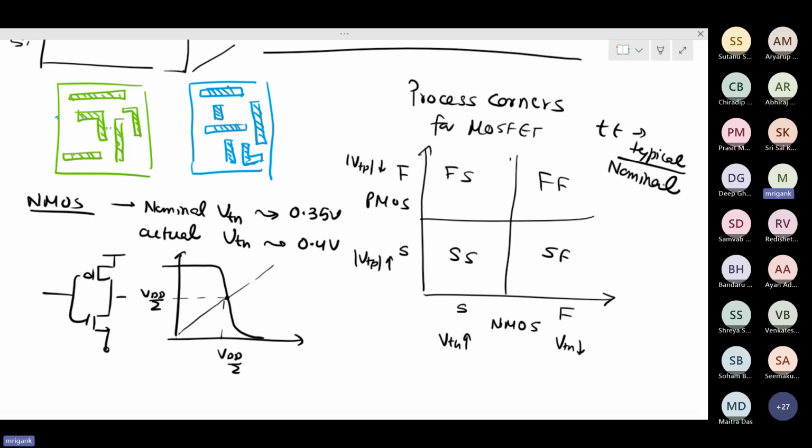In this LTspice, you may not get that kind of model. Right now in this model, you don't have this corner setup. But if you want to emulate, you can always emulate. Just like, if you want to lower the threshold voltage VT in that model, you can go and edit the VT value or the doping value. In the 45 nanometer model which you sent, there it is there in the text file: just slow, fast, and typical. Okay, that is there. Then it is good. So in that case, you can do it directly. Otherwise, in the older models, you can directly modify the VT value.